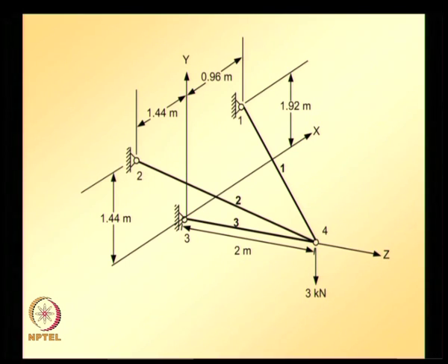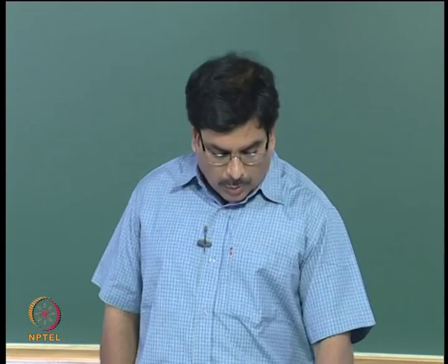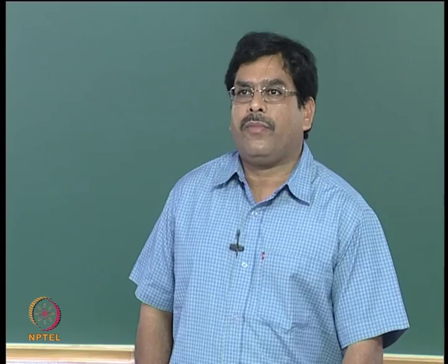And now again here, for simplicity, the element equations are directly written in terms of global degrees of freedom while taking into consideration the boundary conditions. The unknown reactions at the ith node corresponding to 0 displacements are identified as r xi, r yi, r zi, where i takes values 1, 2, 3. It is similar to what we did for 2D plane truss elements.